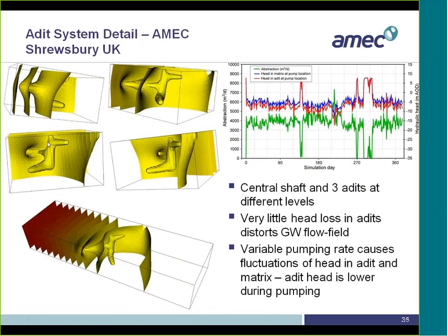They would have this central well, and they'd have these adits at different layers pushing out at different angles into the domain, and they are using the CLN package to model the adits. As you can see, when it's pumping, the CLN heads are below the groundwater cell heads, because these are representing the heads within the adit itself.